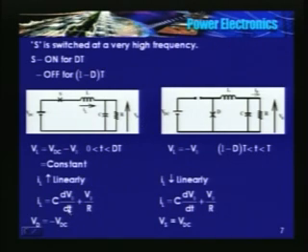See, here I am writing dV naught by dt. At this stage I am writing that V naught is constant. Both are correct, and let us see in what context I am saying this is constant, and here I am writing dV naught by dt. Have some patience. What is the voltage that appears across the diode? The diode comes across the DC supply, so the voltage across the diode is minus VDC. It is blocking.